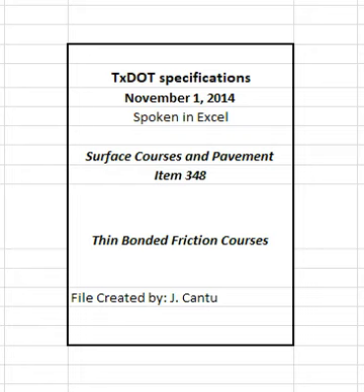2.6.4 Warm mix asphalt, WMA. Warm mix asphalt, WMA, is defined as HMA that is produced within a target temperature discharge range of 215 degrees Fahrenheit and 275 degrees Fahrenheit using approved WMA additives or processes from the department's MPL. WMA is allowed for use on all projects and is required when shown on the plans.